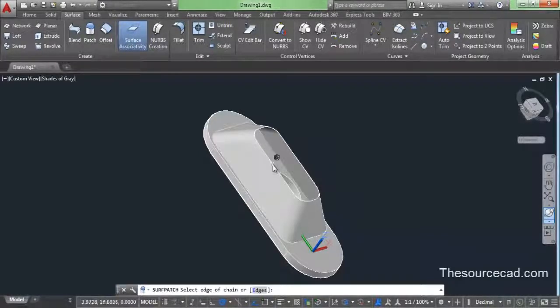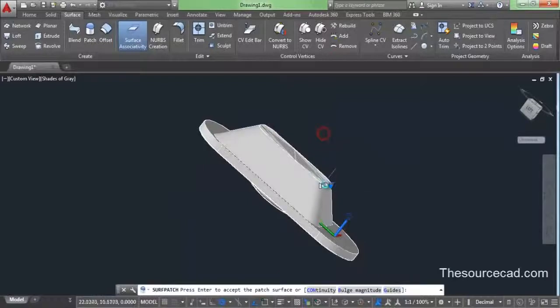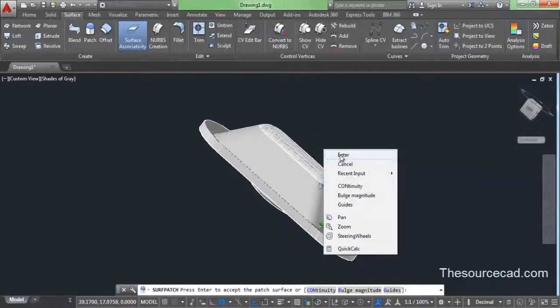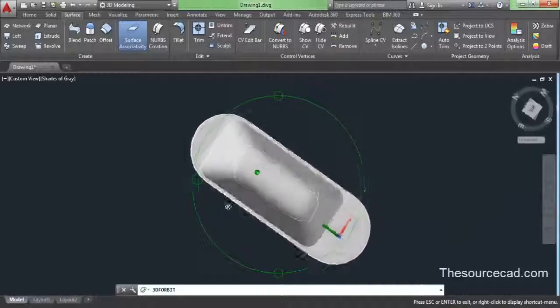So okay, I think it's not been selected. Now go on and select it again. Yes, make a selection now. Yes, here it is. Go on, press enter and click on this small grip, this small arrow grip which you can see here. So click on this small arrow grip and change it to tangent and press enter. And here we have this closed profile.